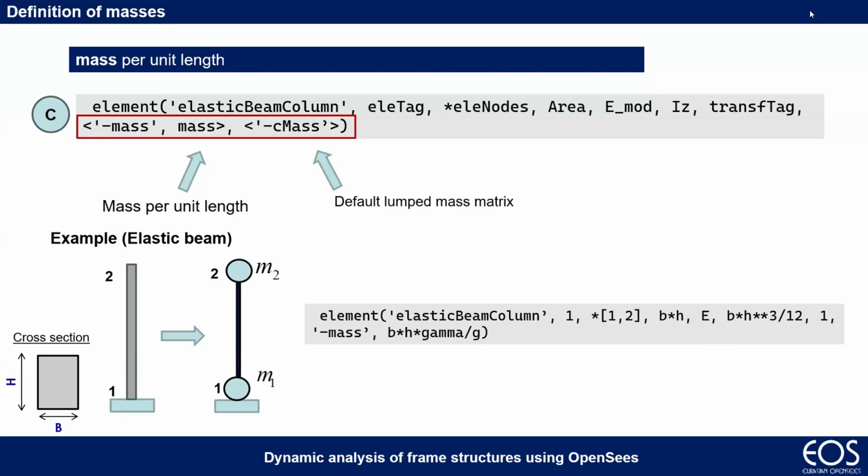How these masses are computed, we can see in this example here. It's just an example that you saw yesterday with Cristoforo. It's just a simple column. If we declare the masses this way, of course, this is just one directional, but you have to declare 3 times or 2 times and 0, then it's computed like lumped mass.